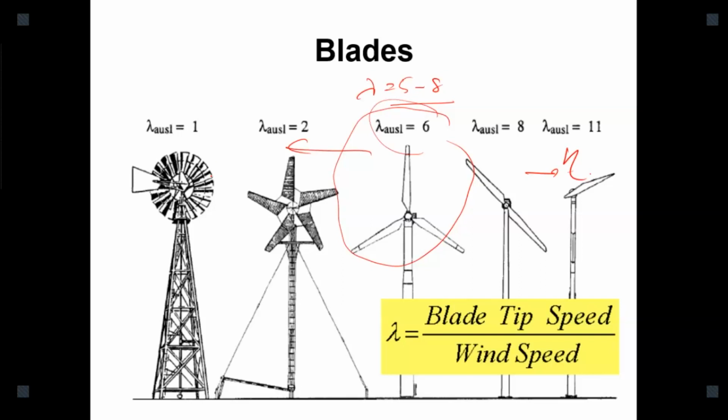Then, why are we using multi-bladed wind turbines? As I explained, energy equals torque times RPM. Where we require high torque applications, we require multi-blade. For mechanical devices, if we need to drive mechanical forces, obviously we require high torque. Maybe a water pump, a grinding mill, any such places.